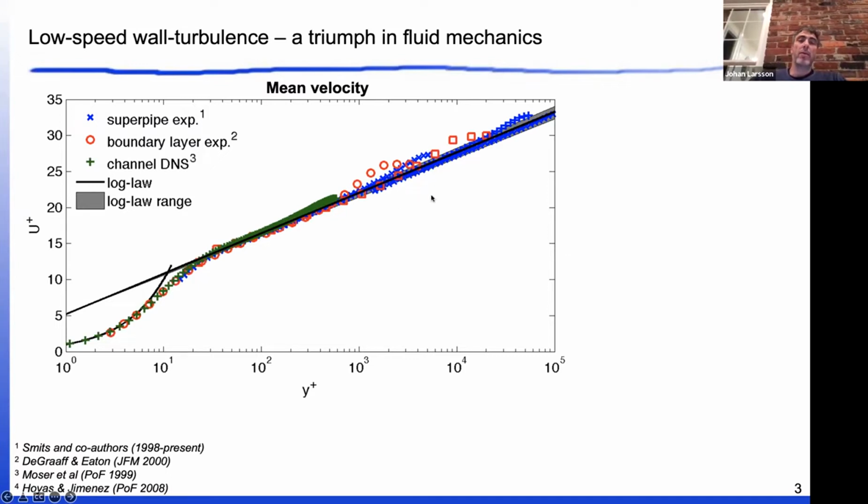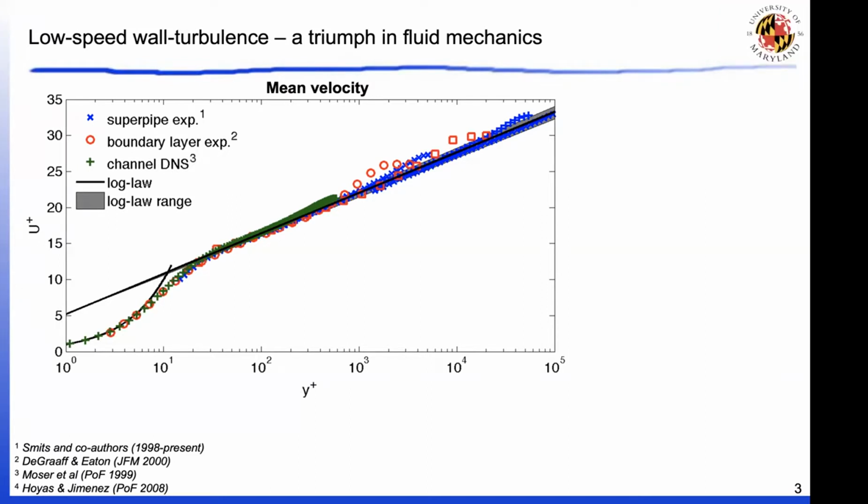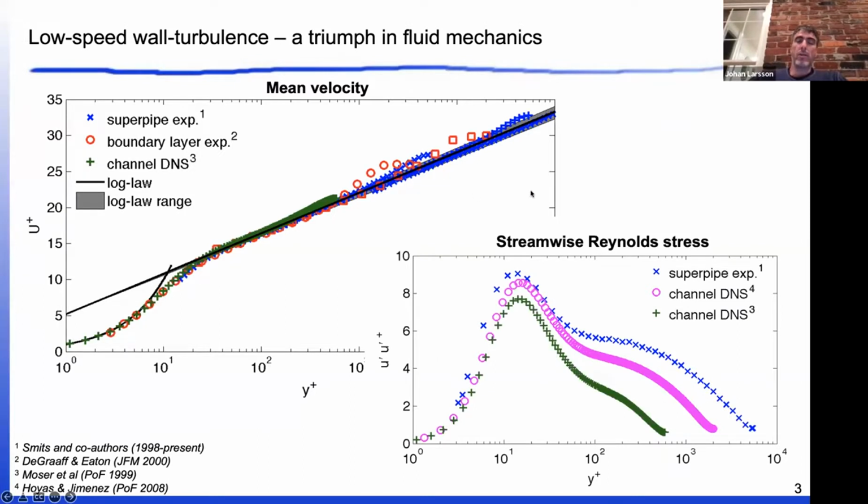And now I would argue that the current debate in the field of incompressible turbulence concerns things like what is the exact slope of the log law and where exactly does it start, for instance. But that's a quick snapshot. Over the past 20 years in wall turbulence, probably more attention has been paid on exactly what happens to the Reynolds stresses. How does the peak magnitude change with Reynolds number? What happens to an outer peak, and so on. Now in Australia, you have some of the best researchers in this area, and you know much more about it than I do. The only reason why I put this up is to show the kind of spread between different results that we see in incompressible turbulence.